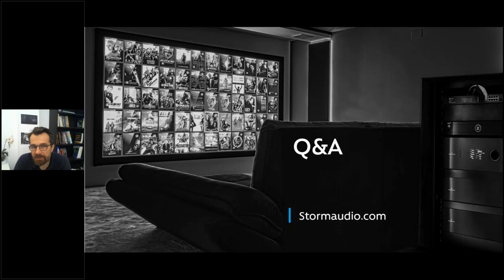What you need to keep in mind is that when you define subwoofer groups, it is basically the main subwoofer that will have the full bandwidth. So the first subwoofer will have the full bandwidth LFE reproduction. So this is the one that is the most critical to adjust, as it reproduces the LFE, the infrabass.